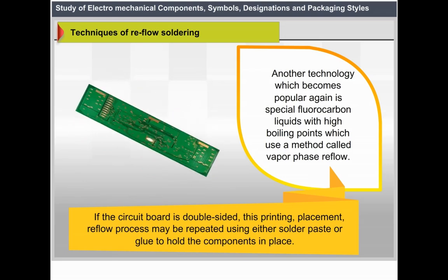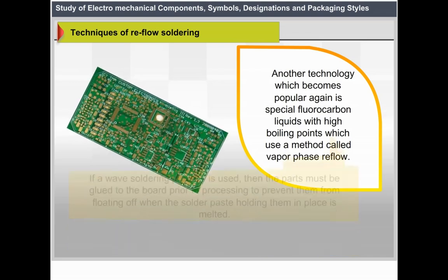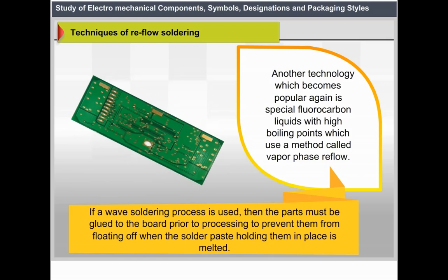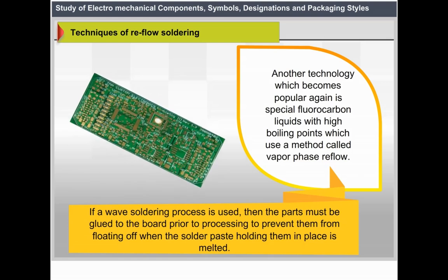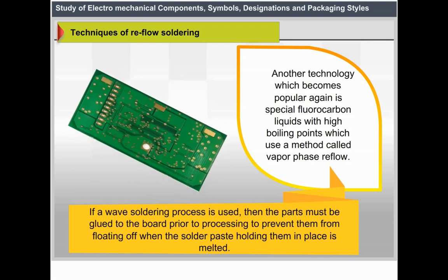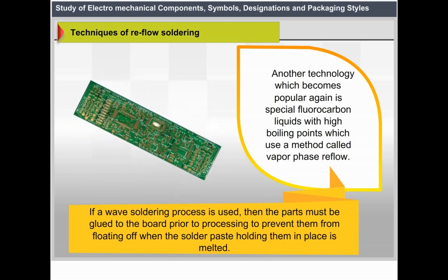using either solder paste or glue to hold the component in place. If a wave soldering process is used, then the parts must be glued to the board prior to processing to prevent them from floating off when the solder paste holding them in place is melted.